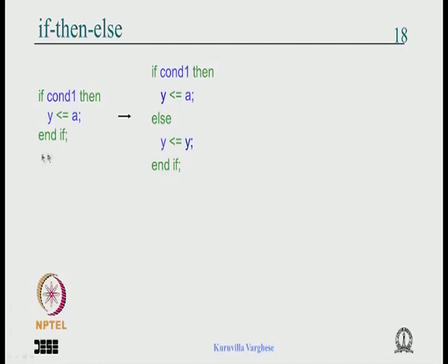So don't ever write like this; if you want a latch, always write like that. And this, as I said, is a latch where if this condition is not met, the output is fed back, you have the output going back as an input, that is what this kind of code achieves. So it is called implied memory or inferred latch. Implied memory because this code implies memory through feedback, or the synthesis tool will infer a latch from this code, that is why it is called inferred latch.